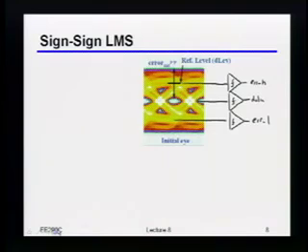Okay, so it turns out there's even a name for this. It's called Sign LMS. Let's say I'm really lazy: I don't even want to deal with the analog value of the input to the equalizer. So the only thing I'm going to deal with is the sign of the analog input and the signs of the errors. This is called Sign LMS only because normal LMS is just called normal LMS, meaning everything is analog.